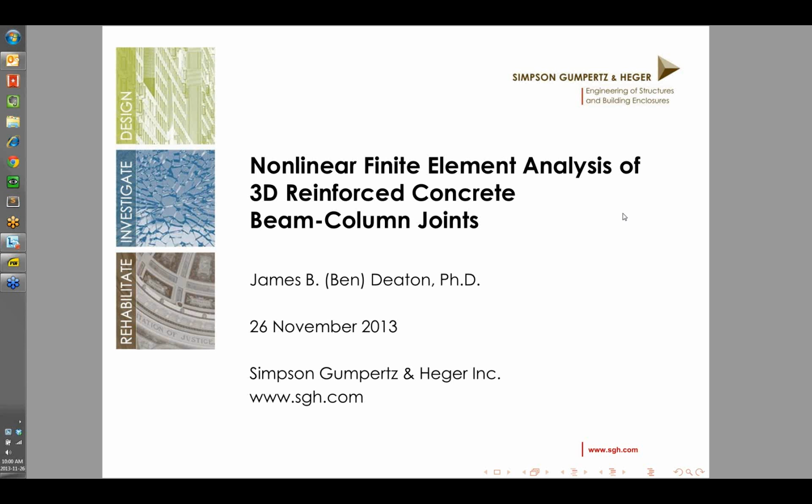So in those cases, what I actually did was I modeled the column axial force using an elastic spring, which had the same stiffness as the rods, and then I used a support displacement to enforce that condition. So this very closely mimicked the idea of the somewhat varying column axial force. But I tried very hard to make sure that it closely matched the response, or the exhibited column axial force.